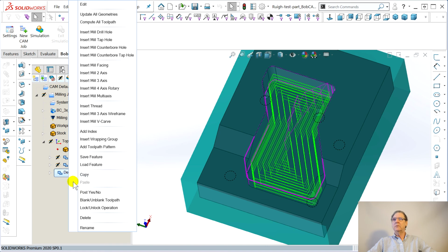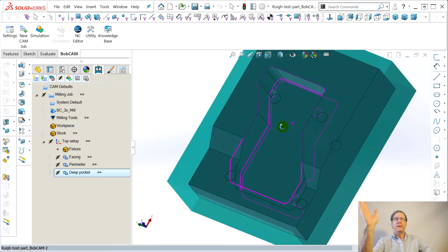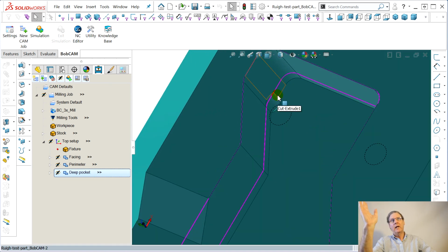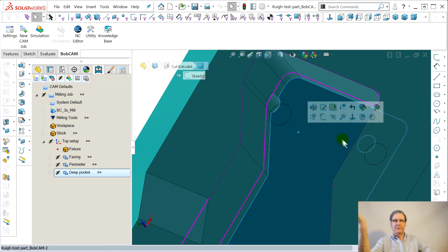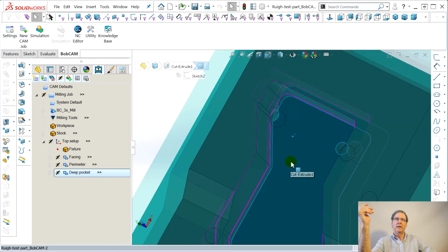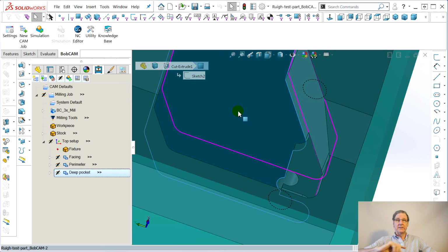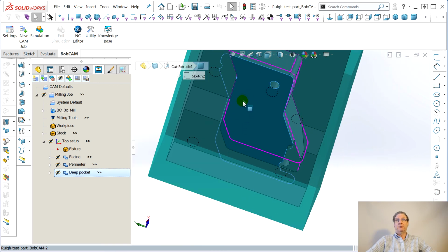Now, we're going to blanket. For SolidWorks CAM and VisualMill, they both had this problem where if you just use the bottom face as a contour to mill, as a pocket, it gets in trouble here because it has to do this arc. It goes around. It doesn't know to bomb straight through and keep this surface matching up here. Same problem down here. Even though this gets drilled out from underneath, it would leave a little bit of stock here. Now, I didn't see that in this program. As a matter of fact, if I just say, take this and do your thing, it actually looks pretty good.